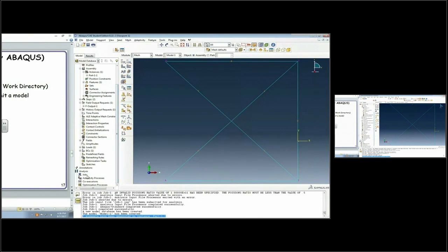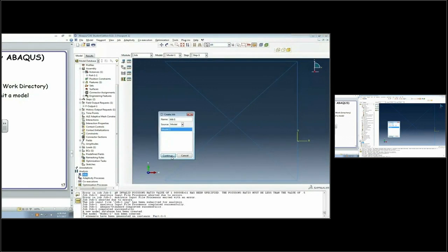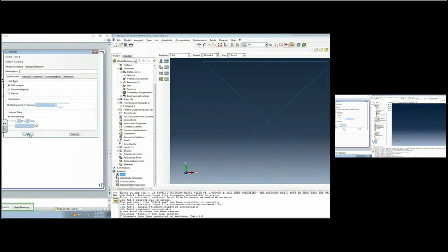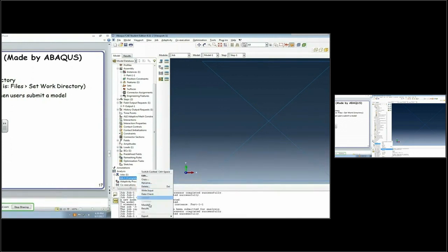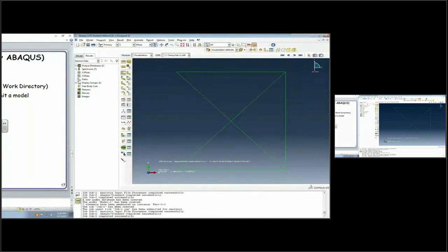So I think everything's done. I create a job. Double click. Submit. Okay. So this is Mises stress, S11.